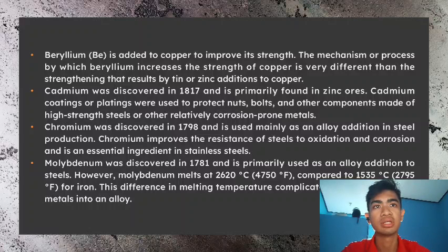The refractory metals are not compounds, but have relatively high melting points. Because of its high melting temperature, molybdenum is used in the manufacture of high temperature heating elements and furnace trays. Work to develop molybdenum alloys for gas turbine applications is one of many studies designed to obtain metals and alloys for very high temperature applications.